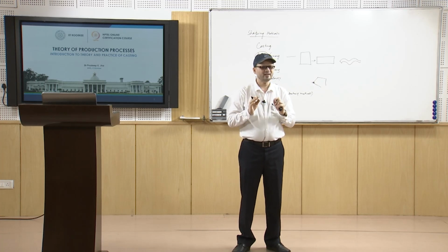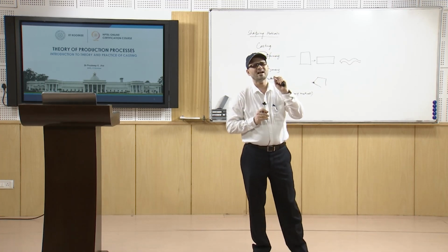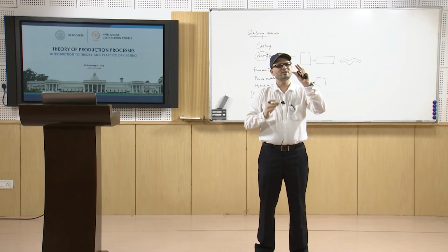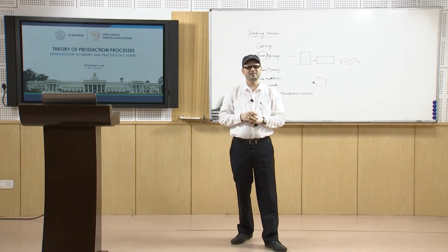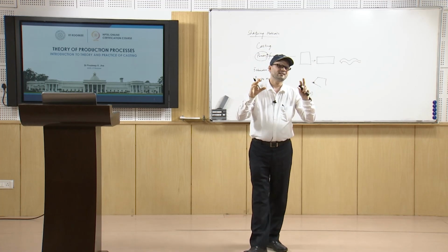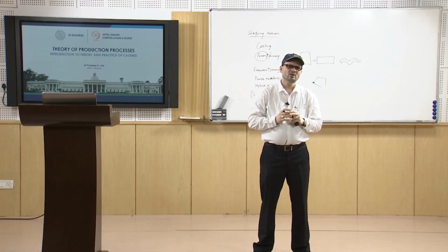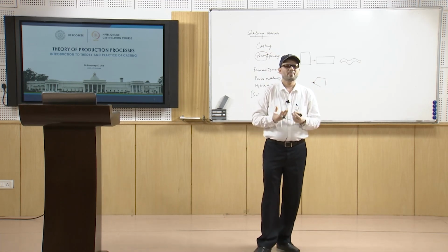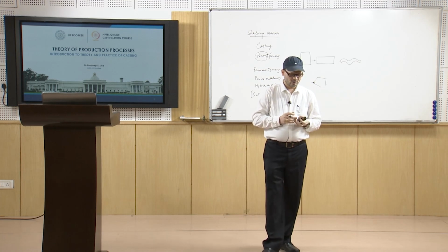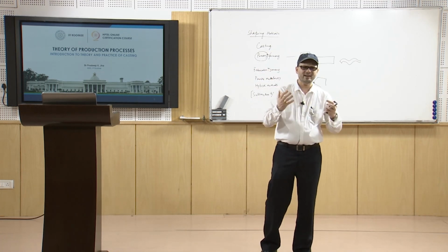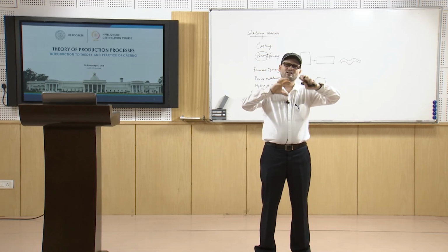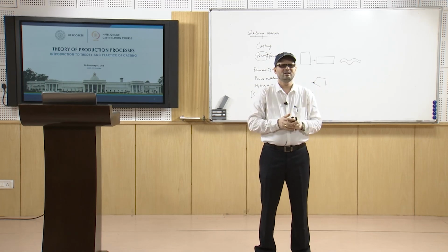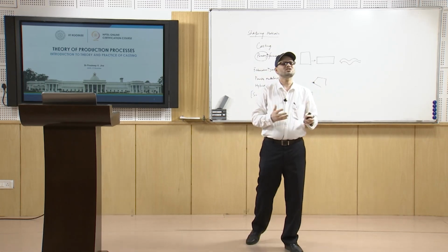Shape and intricacy. So, in casting you can have any shape. Once you have any design in mind, you have to see how to make the mold. So, the mold or cavity will be made by making a replica of the product which you are planning to make, and then you remove this replica and get a cavity. So, this way you can have any shape of the material,